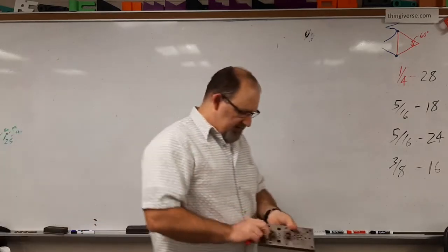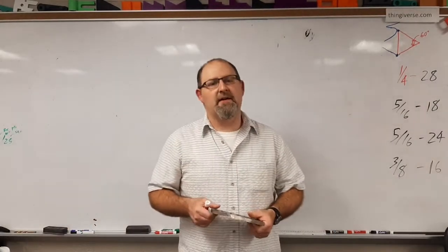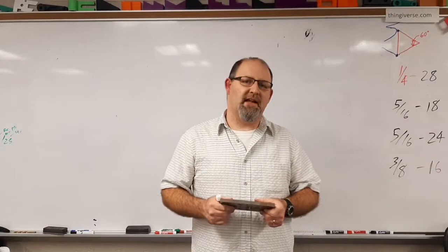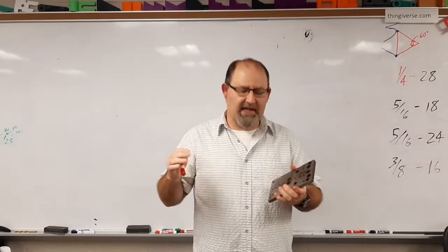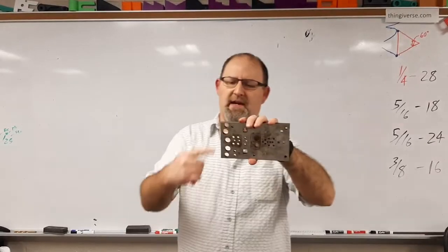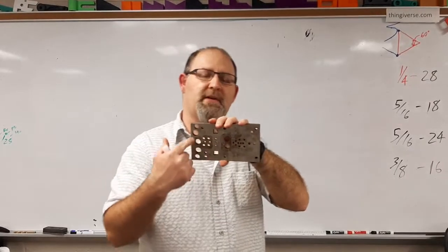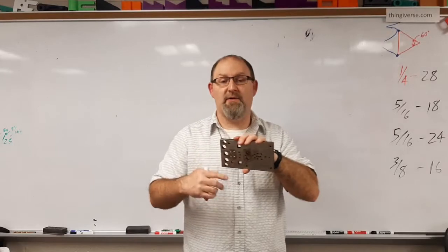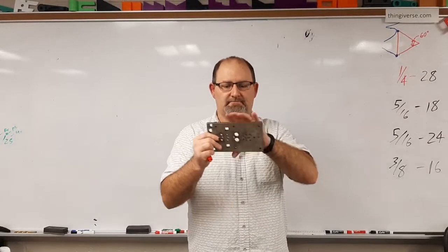So, I used to know a guy who worked at a tool and die manufacturing plant. They did a lot of die stamps, and they did a lot of datum dimensioning. Okay, so let's take, for example, this plate right here. If we had to locate all of these holes quickly without getting a really messy drawing.